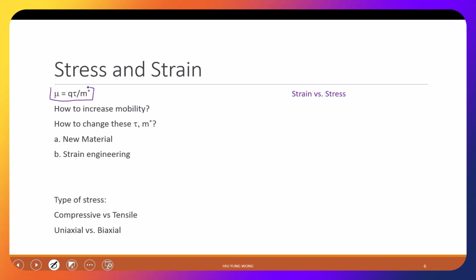But if you have learned solid state physics, you learn that mobility depends on the mean free path time and the effective mass of the electron. Not lifetime, sorry. When your electron is moving, from the semi-classical picture, they are free and eventually you will hit something, right? Either lose energy to phonon, hit other electron, get scattered by the Coulomb charge. So this is the mean free path.